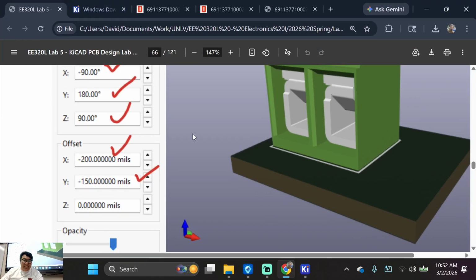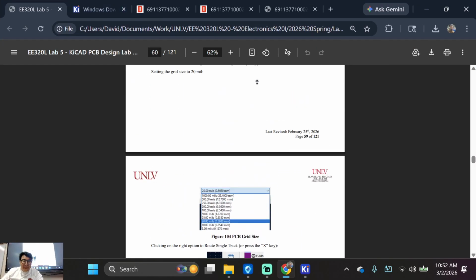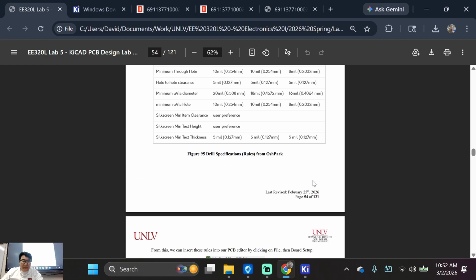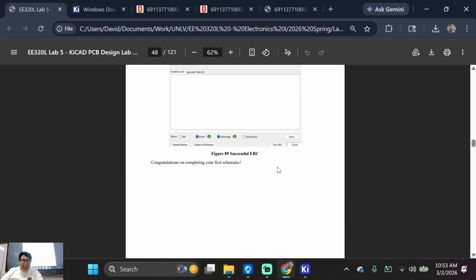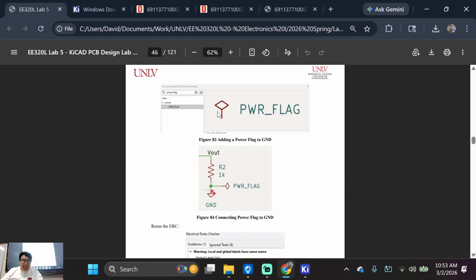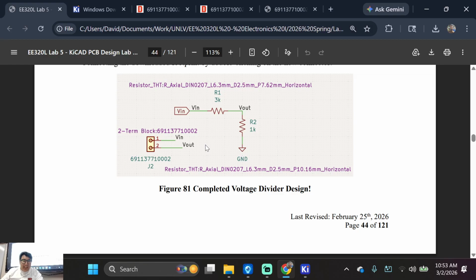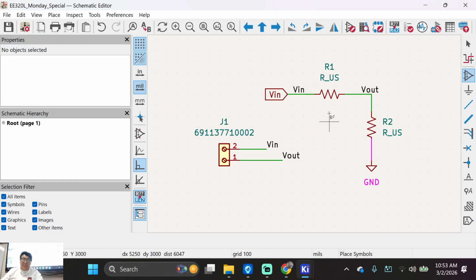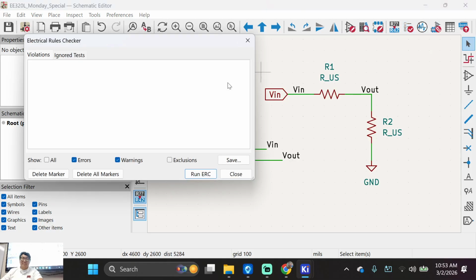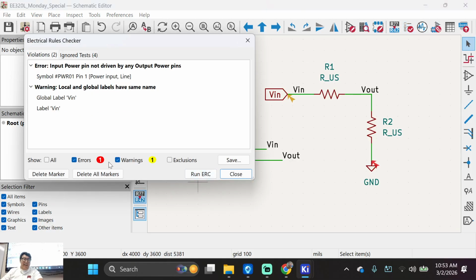Is that it? Let me check. Let me see. Was that really it? Okay, let me check. Okay, we're gonna need a power flag. But okay. Like that? You like that? Okay, we're good. We're going ERC. Let's do an ERC, okay? I want to generate something funny. ERC stands for Electrical Rules Check. It's going to just check if it works. Run. Aha. It says it needs to be driven by power.